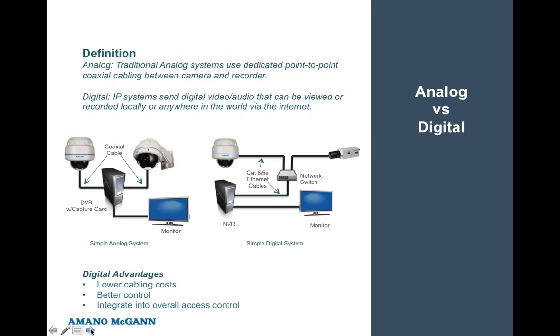And these are all IP devices, so you don't have to run a lot of cabling. Before, you had to home run everything back to a single room. But now you can have it by door, and it really reduces the cost in terms of how you cable and how it manages each specific door.